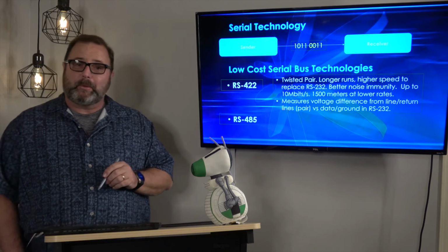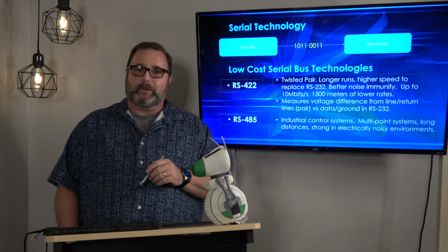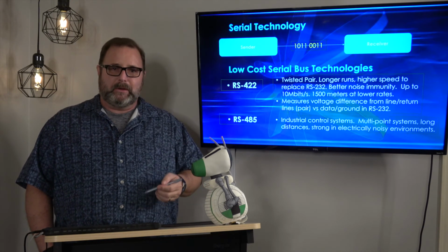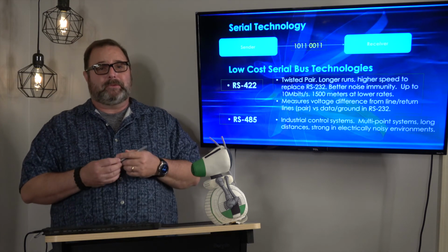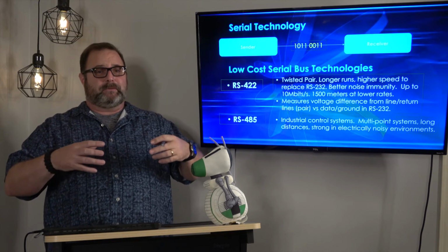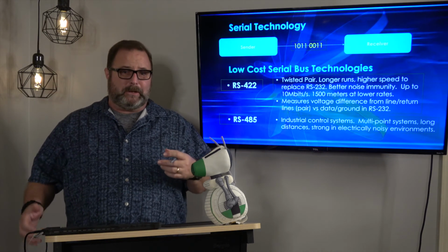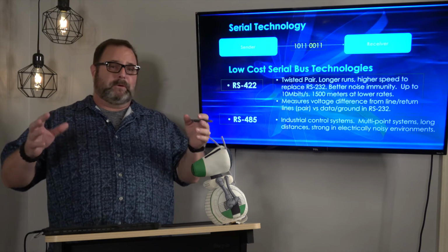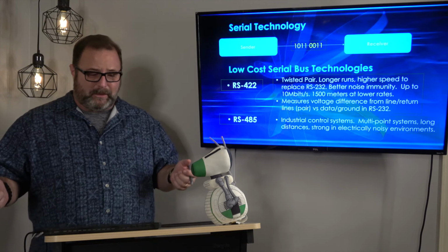Now there's RS485, which is kind of another industrial one, and it's used for control systems. And it is really, really good for noisy electrical environments. Remember, I've said that you can have electrical interference on cables, right? And if that's a problem because your machines are creating a lot of electric noise, because whatever you're doing uses a lot of power on a lot of different devices, okay?